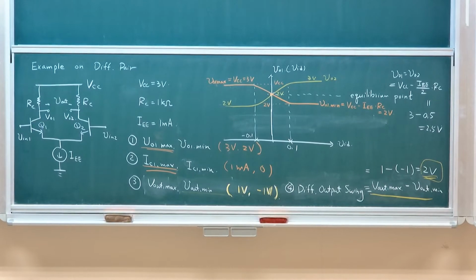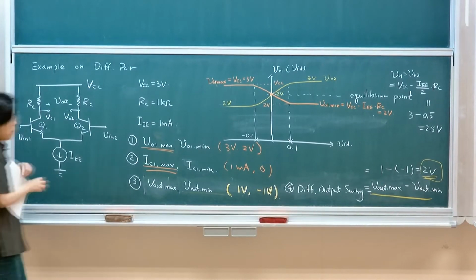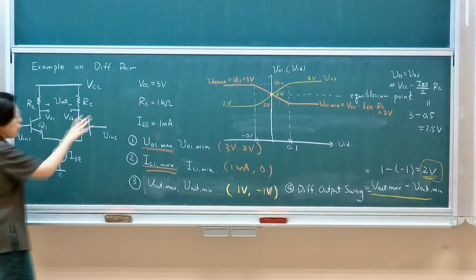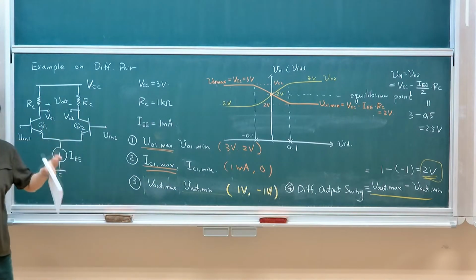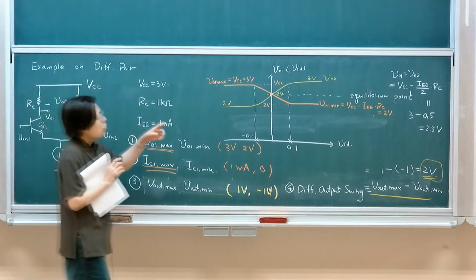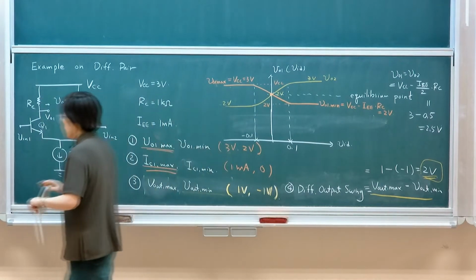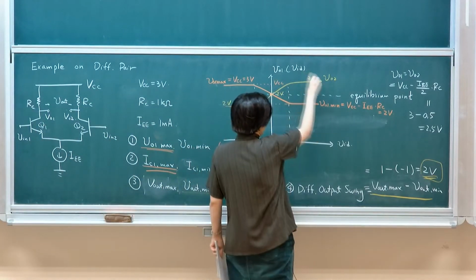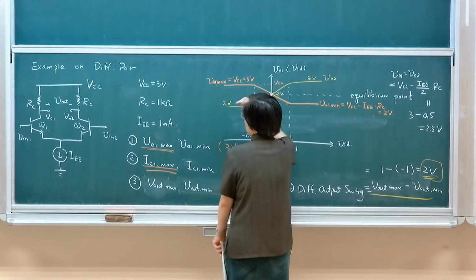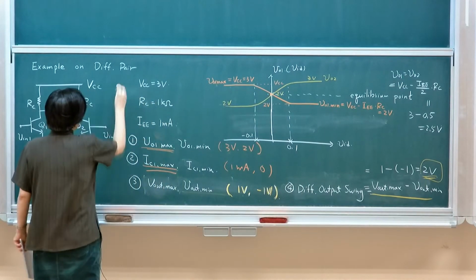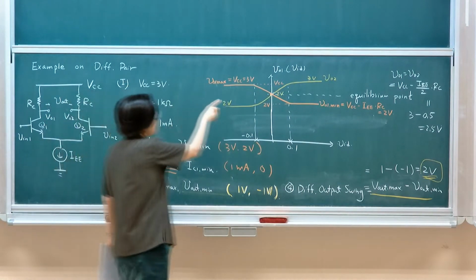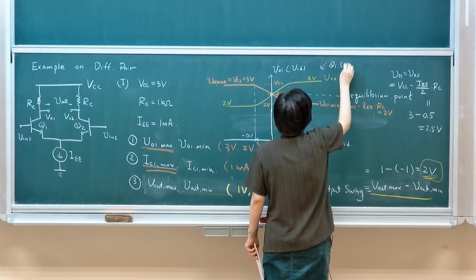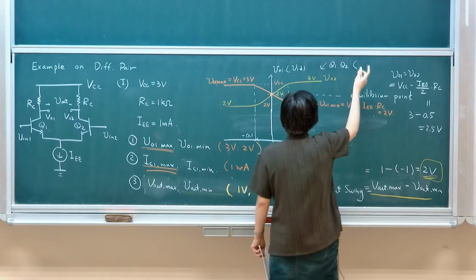Okay, so this is when you see your minimum. The whole following analysis is based on this: if I'm swinging my differential pair, the transistor, no matter where it goes, only has 2 states. Under this setting, let's say this setting is number 1, your Q1, Q2 will only be in 2 modes.